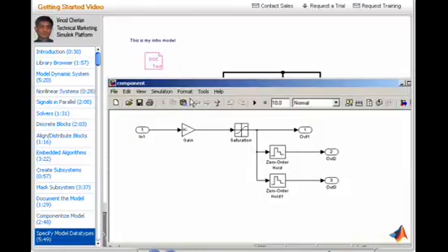Since we can automatically generate code from this model, we might as well design the data types for this component in the Simulink model itself, and Simulink allows you to do this. So as a designer of this subsystem, I know that I want to implement this on a 16-bit processor, and so I'm going to have to fix both the input and the output interfaces to use 16-bit data types. Let's see how this is possible.